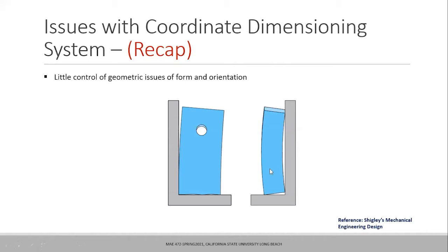And similarly in this figure, even if throughout the length you can have the thicknesses as per the drawing, it is truly not in form because there is some curvature out there, and it may be possible that the curvature is coming because the raw material that was used has a specific curvature, was not properly flat, or when the process of fabrication started the top and bottom surface was not properly milled.